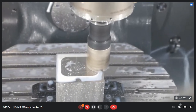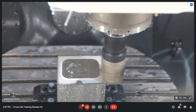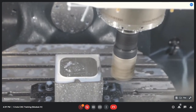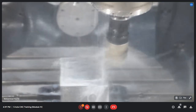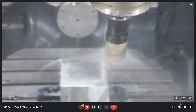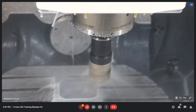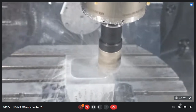So now the depth of cut will be -2, in total. So now I'm going to use the coolant supply. Okay. The depth of cut is 1 mm, but the total depth is -2.